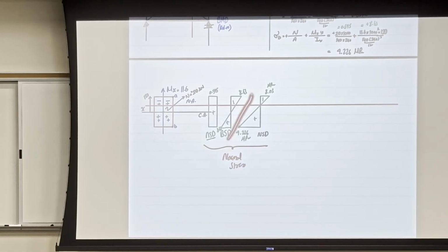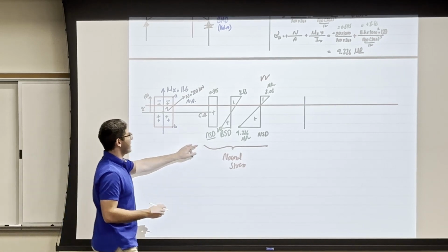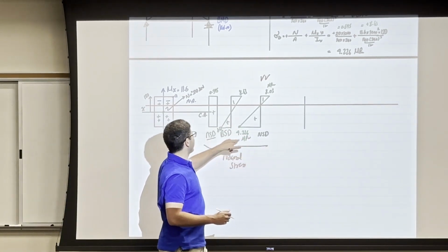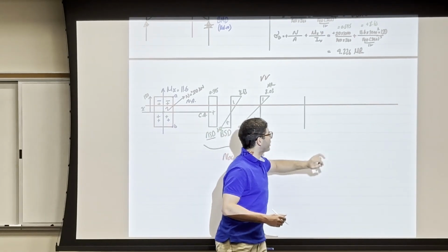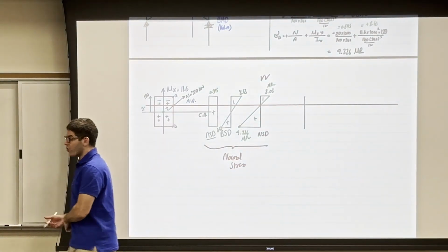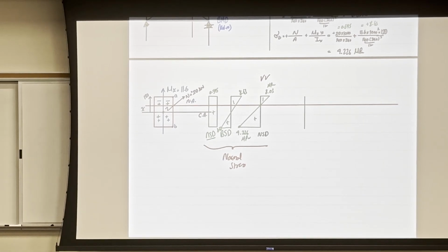I'm just breaking up the diagram, and this is the final diagram. So what I want you to draw, I want you to draw this. Second thing, I want to calculate the normal strain. So the normal strain, you can also calculate it graphically, which is getting me the strain for the ASD alone, and then an axial strain here, and then a bending strain here, then to get me the final strain. Or you can use the diagram. Also, you can use the equation right away.